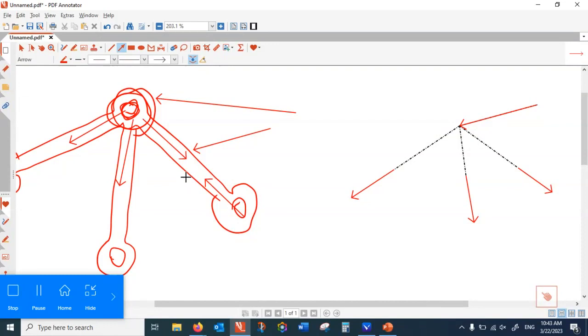And in some cases, before doing the method of joint, you need to find the reactions. And to find the reactions, what do we do? We solve the entire structure. When you solve the entire structure, that gives you the reactions. So yes, the entire structure can impose three conditions. Because it's a rigid body, the forces are not colliding at one single point. The free body diagram has capacity to rotate. So then you have three conditions, you can handle three unknowns.